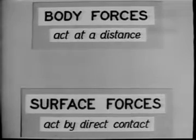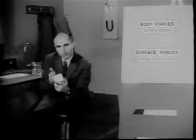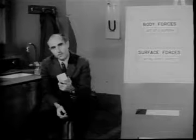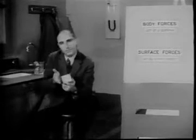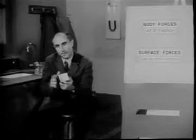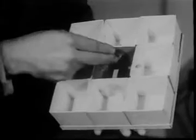While body forces act at a distance, surface forces act by direct contact between the particle and the surrounding medium. And as the name implies, surface forces are exerted directly on the six surfaces or faces of the cube by the surrounding fluid with which it is in actual contact. On each face of the cube, equal and opposite forces are mutually exerted between the fluid inside the cube and the fluid outside.